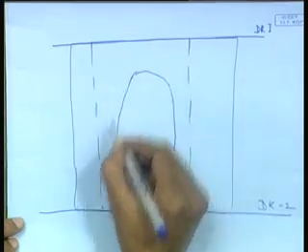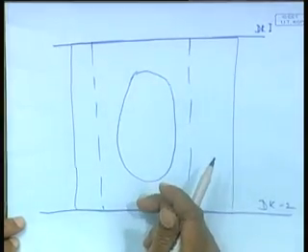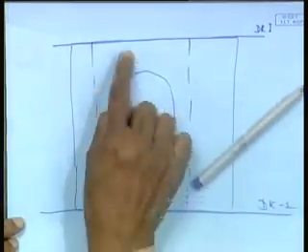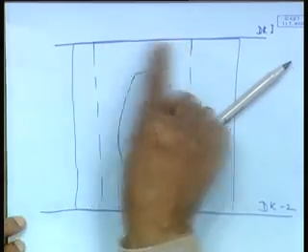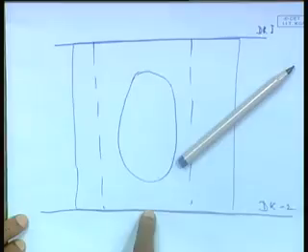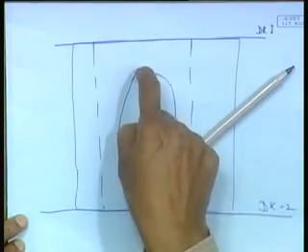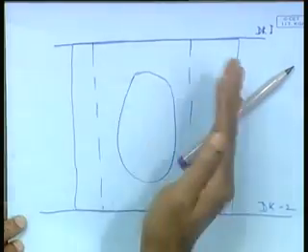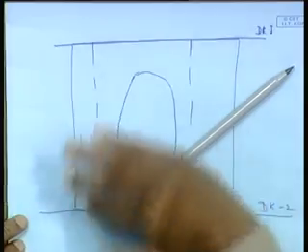This is, say, the side accommodation bulkhead, and you have the stiffeners. So in between it will buckle between the stiffeners. That buckling will not occur at the welded edge, because there it is welded, so that will be a straight line. Again here it is restrained, but in between it is free, so this will buckle, it will bulge out like this, in both directions.